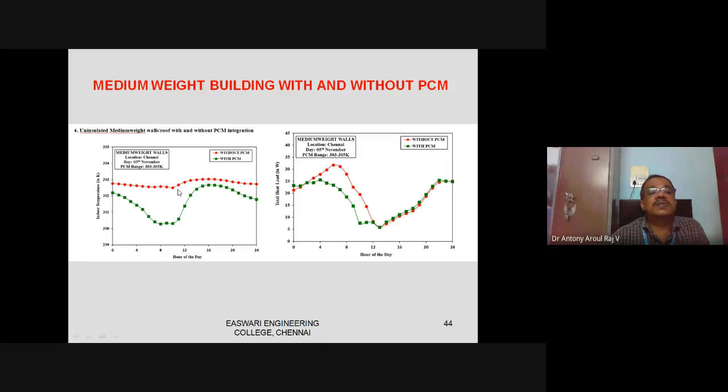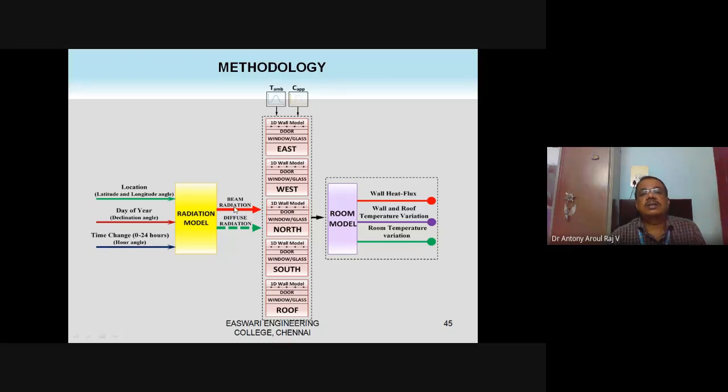So what is the reason? Because of the phase change temperature. If the temperature is moving freely like this, it means the phase change temperature may not be matching. Because of that, if it is in the liquid region, the temperature swing will be there again. So with the PCM, a temperature range is also possible if it is in the liquid range only. That means you have to select the PCM with the correct temperature range, otherwise a problem like this will be there. Now you can see without PCM the heat flux is this much, and with the PCM the heat flux is this much.